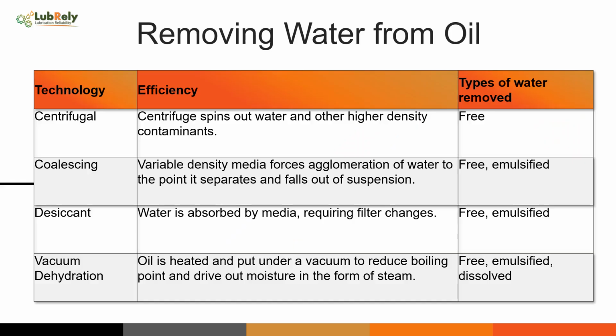Removing water from oil. Once the sources of water contamination have been controlled to the extent possible, there are several methods to remove water from oil. Methods that can be used successfully for different applications include settling, heat, chemical demulsifiers, filters, coalescers, centrifuges, vacuum dehydrators and electrostatic treatment.